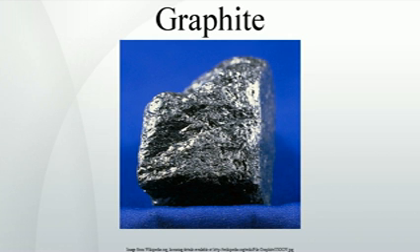Steelmaking. Natural graphite in this end use mostly goes into carbon raising in molten steel, although it can be used to lubricate the dies used to extrude hot steel. Supplying carbon raisers is very competitive, therefore subject to cutthroat pricing from alternatives such as synthetic graphite powder, petroleum coke, and other forms of carbon. A carbon raiser is added to increase the carbon content of the steel to the specified level. An estimate based on USGS US graphite consumption statistics indicates that 10,500 tons were used in this fashion in 2005.